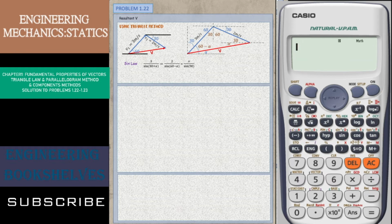That is not yet our final answer because we are looking for the resultant V. For us to solve for our resultant V, we are just going to use either ratio with V over sine 90, but remember sine 90 is equal to 1. So we are just going to use any of the two. I will just use this one: 2 over sine 60 minus alpha. So our velocity will be 3.61 meters per second. That's how we solve using the triangle method.